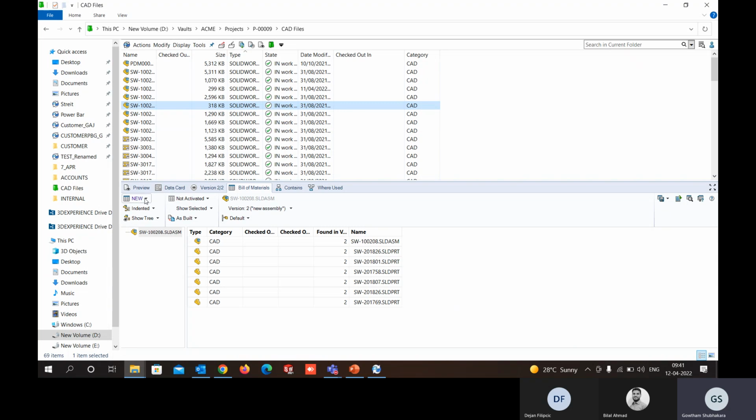Coming to this section, we have a first drop down here, that is the type of bill of materials. In PDM, we can create multiple bills of materials, based on the columns, we can create our own bill of materials and define it. We can define what columns need to be visible whenever you select any part, assembly or drawing, what should be visible in the interface and exported. In that way, we have created multiple BOMs here that you can see.